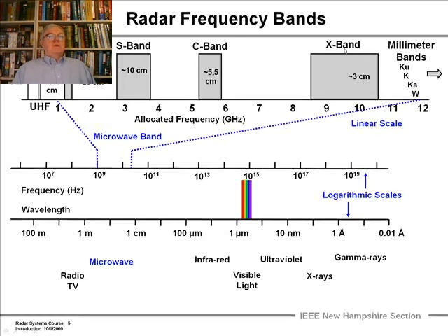Now, I deliberately put up here X-band, C-band, S-band, L-band, UHF, and VHF. If you're going to go through this course, you're going to learn these in a snap, the same way pi is 3.14, 22/7, as you learned in algebra and geometry. You're going to learn X-band, you're going to think 3 centimeters, about 10 gigahertz. Same thing, S-band, 10 centimeters, 3 gigahertz. L-band, 23 centimeters, about 1.25 gigahertz, and likewise. Okay, now let's move on.